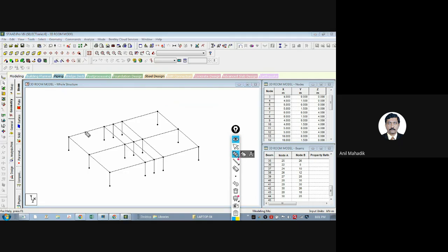So our mistake was, see, our distance should be from the origin to the plane of the mirror. Now this is my mirror plane, and my origin is also here. So that means my Z distance is 0 in this case. Correct. And that's why there was an error. But if your plane is somewhere here, then you need to give a negative Z value. Okay.